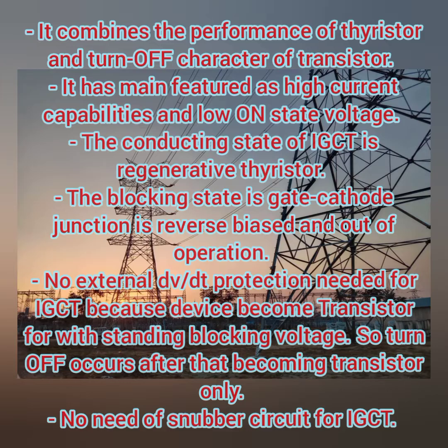Then the conducting state of your IGCT is a regenerative thyristor. Then in the blocking state, the gate cathode junction is reverse biased and out of operation. So it is like a normal thyristor for conducting and reverse blocking states.